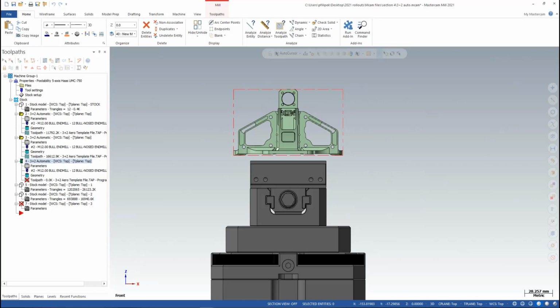And if you want more control, then we have semi-automatic and manual. So if you have a part that's kind of simple, maybe we can go to semi-automatic and maybe just define a certain plane that we want that tool to rough from. And we could have it pick the rest of the planes automatically if we wanted to, or we have full manual mode, kind of like what we did here.